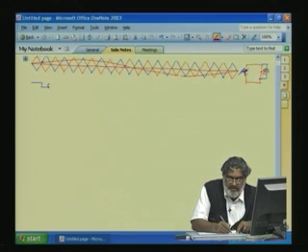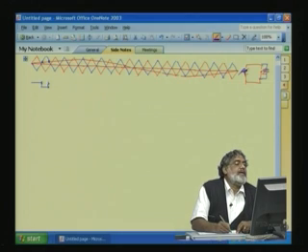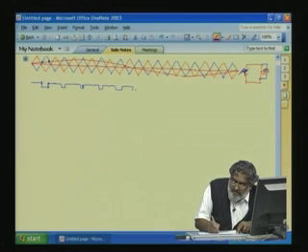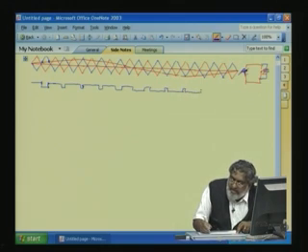So, we can see this comparison, we can take it this way, that is the second one here. During this portion, the triangle is greater than the sine wave. So, we are all the time comparing the blue triangle waveform and the modulating sine wave. Whenever sine is greater than the triangle, the top switch is on.